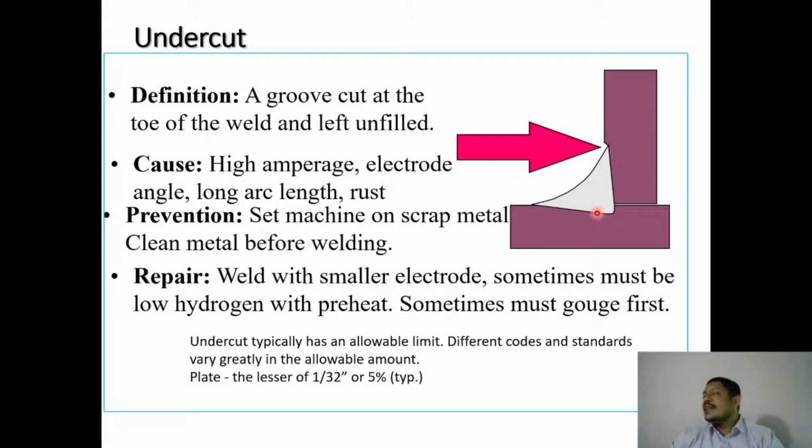Mechanical cleaning processes are available, or some kind of chemical cleaning process, performed on these areas to ensure that no grease or hydrocarbon is present on the weldment area, which may cause further defects. So you have to check the parameters and properly clean the weld to ensure that no undercut is happening on the weld.